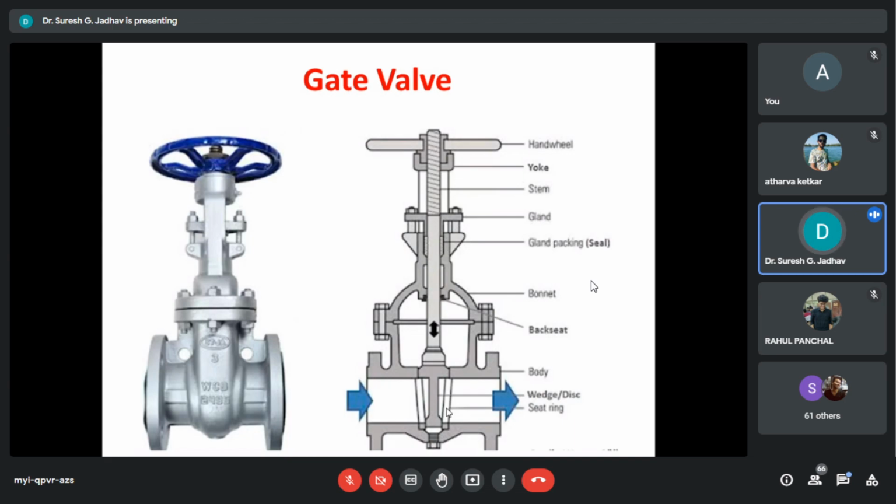The bonnet connection shall be flange, male and female, tongue and groove, or ring type joints. In low pressure rating valves, it may be flat face. The bonnet gasket is selected to suit body bonnet connection.